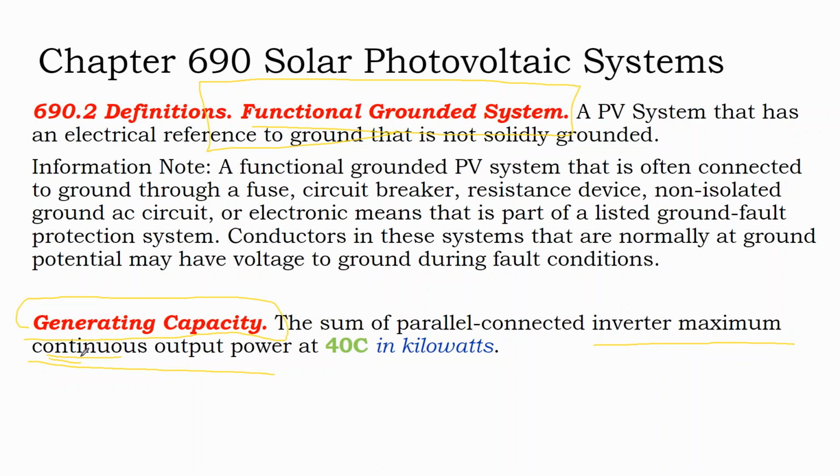Let me tell you, if you're relying on that burst capacity, don't, because a lot of heavy loads like heating loads or air conditioning loads that surge, they surge for longer than 1 minute. And these surge load capacity, extra boost capacity of the inverters, by nature are not designed to last longer than 1 minute. So the burst capacity on an inverter is less useful than you think, but you'll open up a